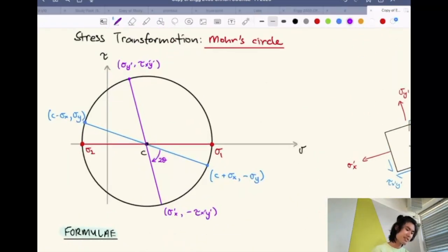These points here, the stress 2 and the stress 1, do you guys remember when I was talking about your maximum and minimum moments of inertia? So that's essentially the equivalent of the maximum and minimum, but they're not really maximum minimum. They're called the principal stresses. Actually, yes, they are. You can think of them as minimum and maximum. They're called the principal stresses, and they'll always be sitting on the x-axis because they're at the very extremes of the circle.